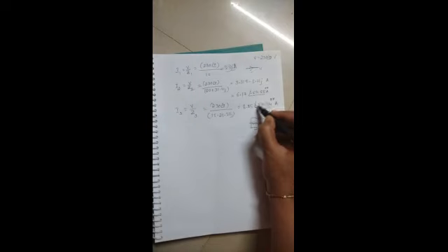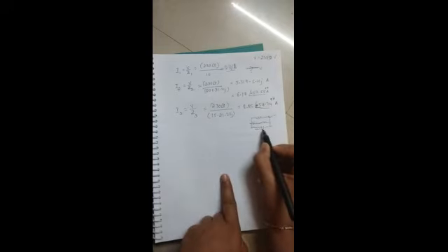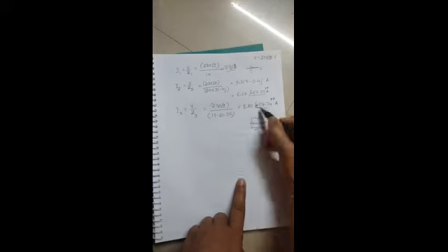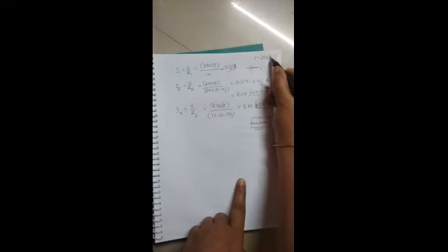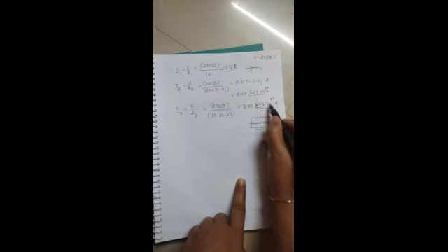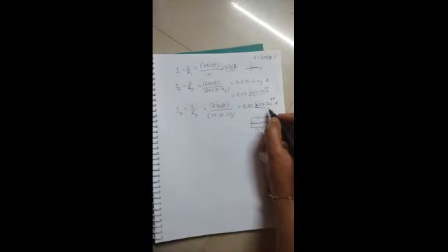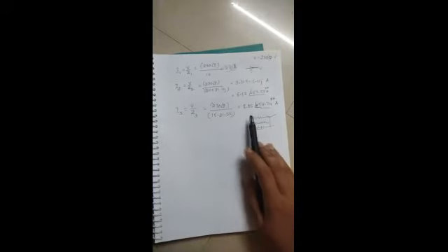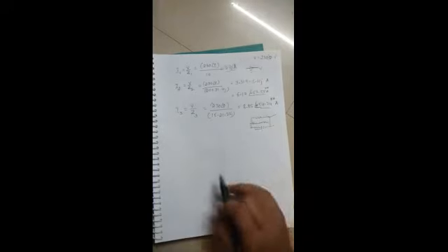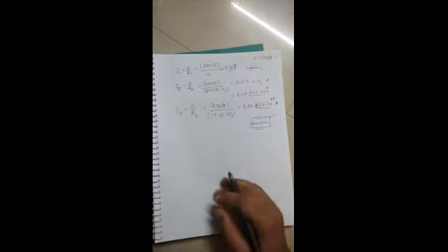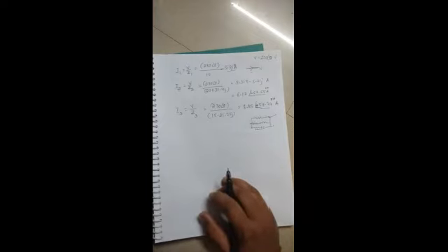The current angle is negative for I2 and positive here. This means the current in this circuit leads the voltage by 54.74 degrees. You can analyze this; if not, don't bother much. This is how we need to analyze it. We are going to deal with a few more numericals on this, so you can easily understand it.